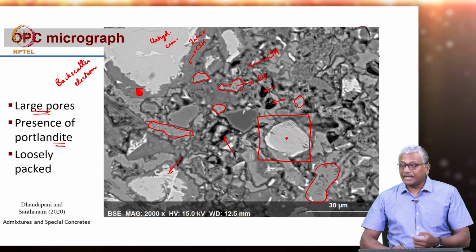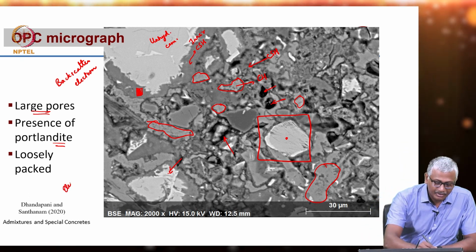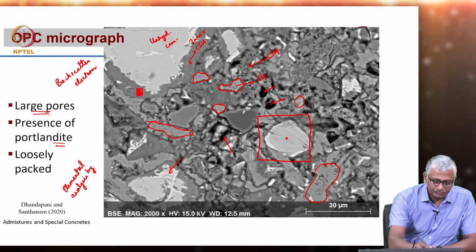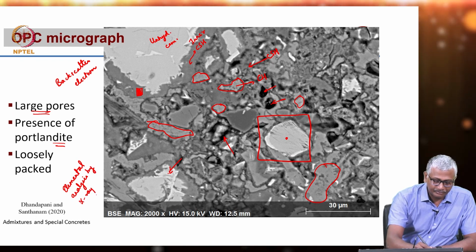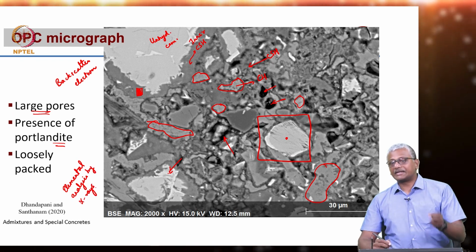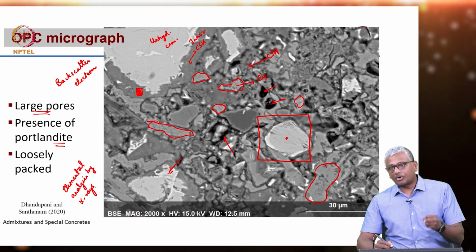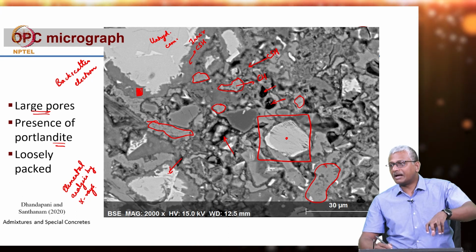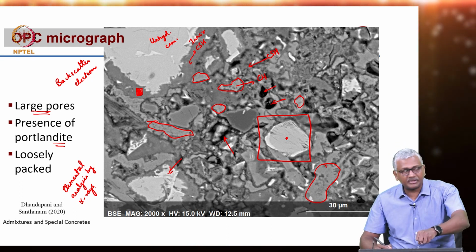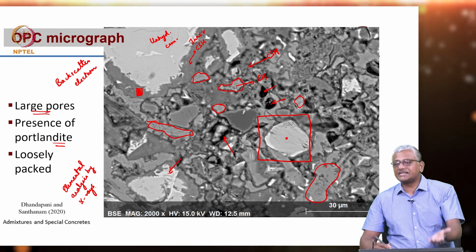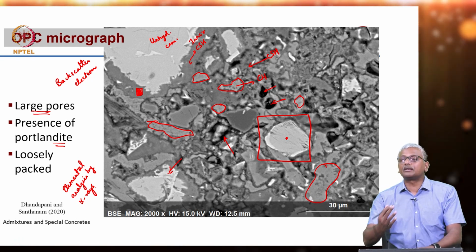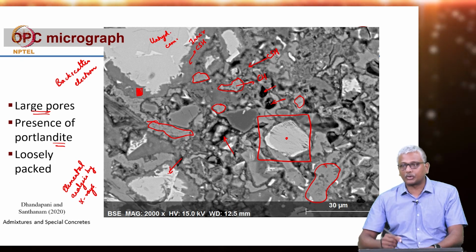So, that is called elemental analysis by X-rays. We are collecting X-rays from the impinging electron that is generating high enough energy transitions in the sample atoms, and these X-rays that you are collecting out of the system can then be analyzed for the chemical composition of the phases you are looking at.